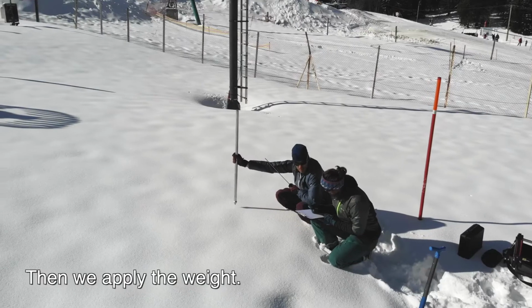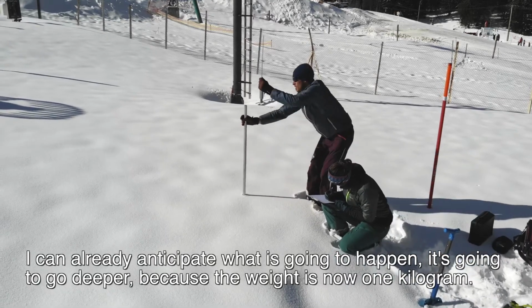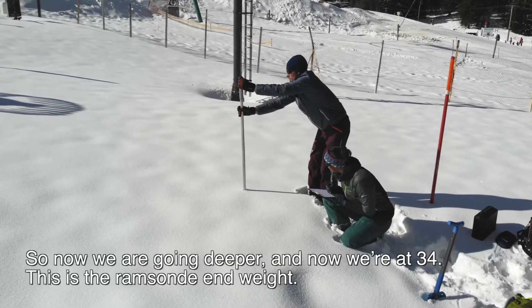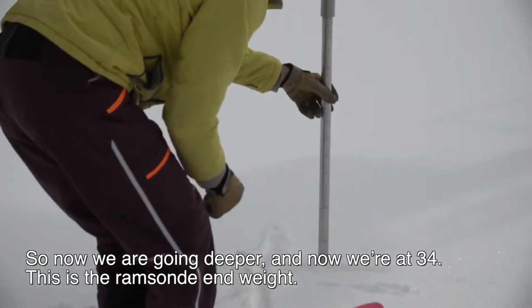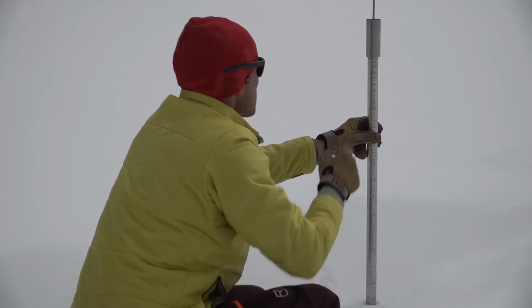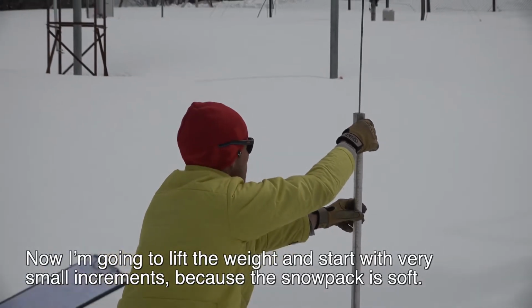Then we apply the weight, and I can already anticipate what's going to happen. It's going to go deeper, because now the weight is 1 kilogram. So now we're going deeper. And now we're at 34. So this is the Rammsonde and the weight. 34. Now I'm going to lift the weight, and I'm going to start with very small increments because the snowpack's soft.